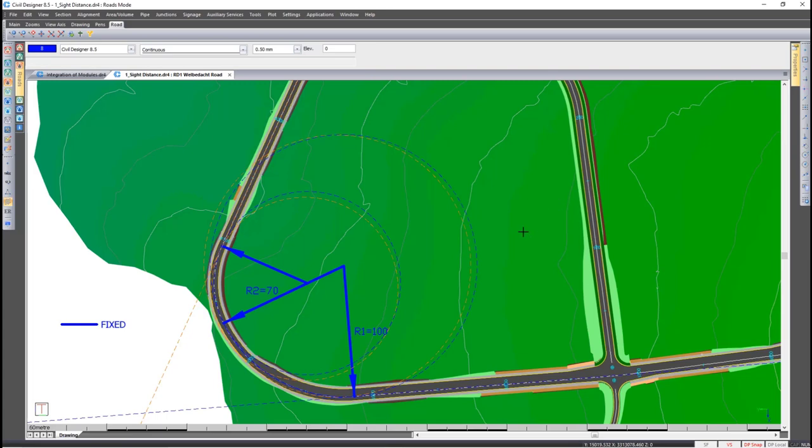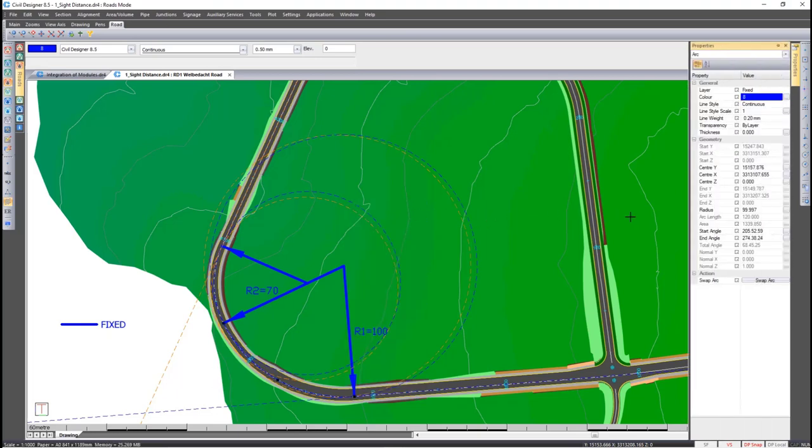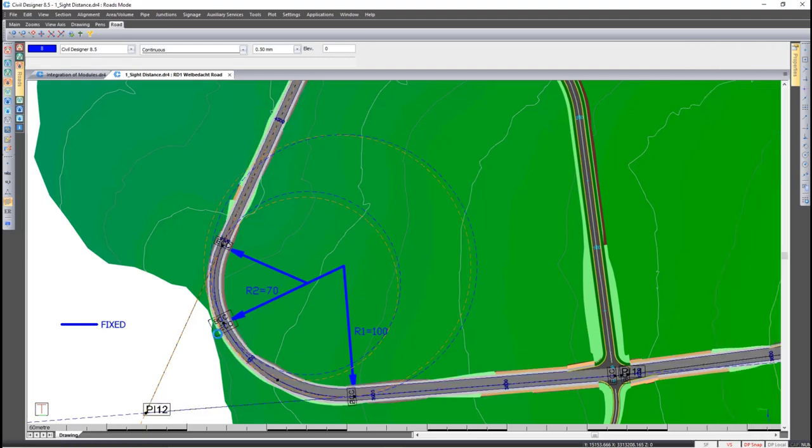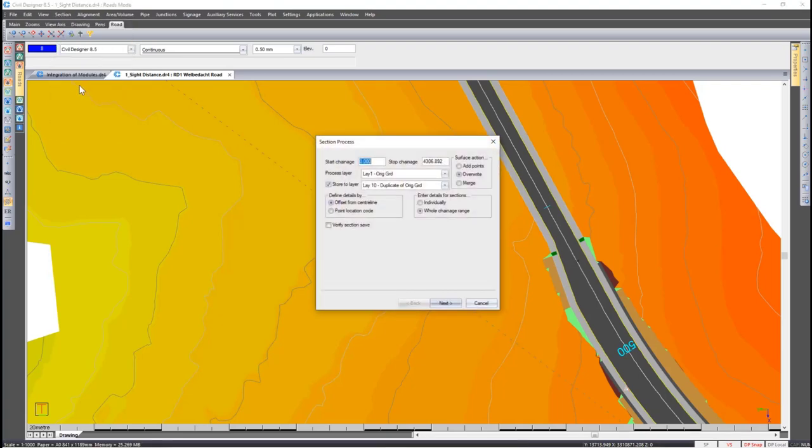Let's take another look at the new curve length in the properties. We can see that it's been updated to 120 and the road embankments fall within our survey. Moving on to our last function, looking at the cross-section editor function to add fill benching. I'm going to start off by duplicating the road ground layer. This will assist to understand how the benching is calculated.